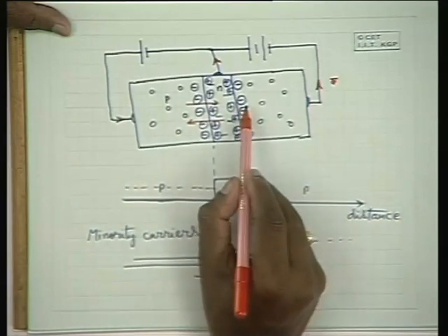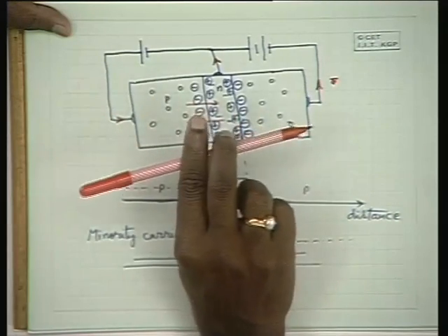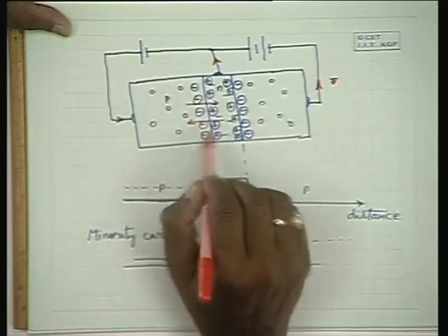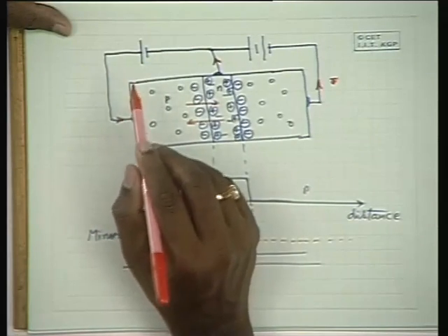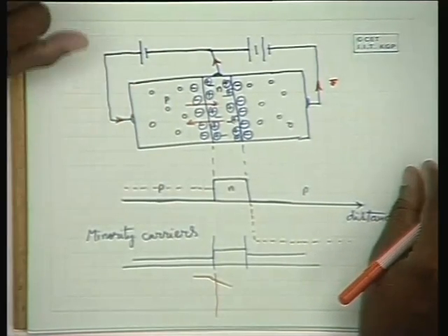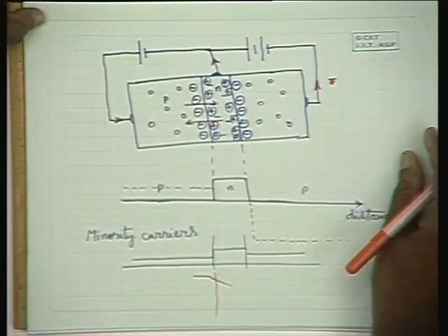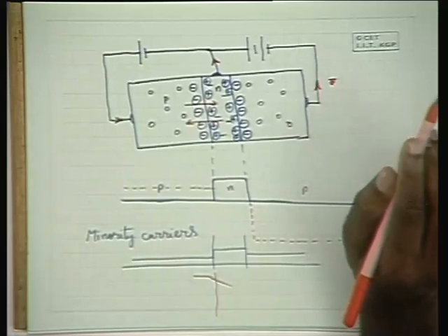And this injection of the holes into the base region, or diffusion of these, naturally depends on this forward potential here, this junction potential between the emitter to base junction. Any questions on this diffusion of the holes from the emitter side into the base and the drifting of these injected holes into the p side by the reverse potential applied across the base and the collector?